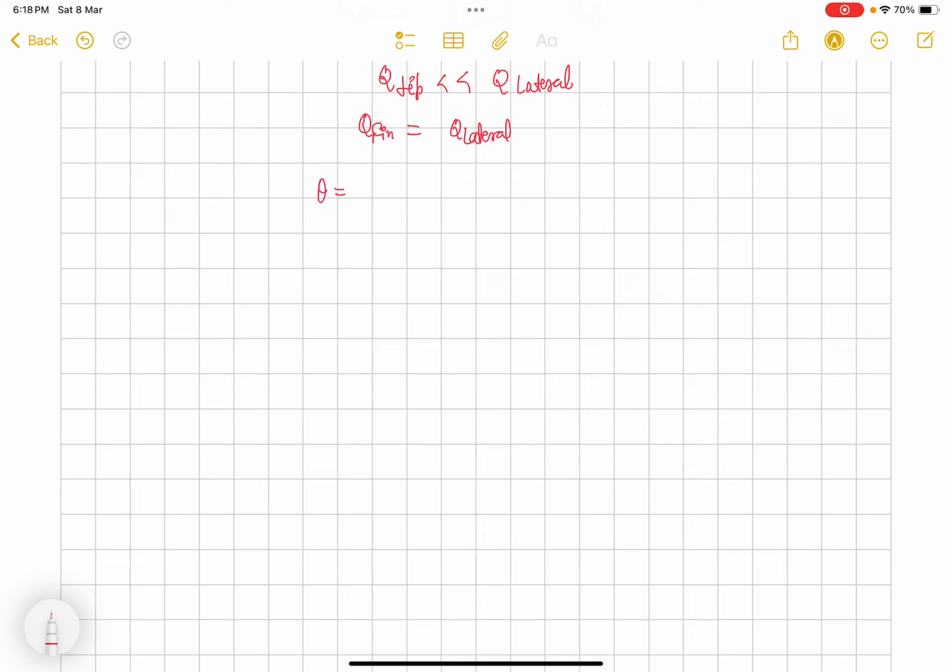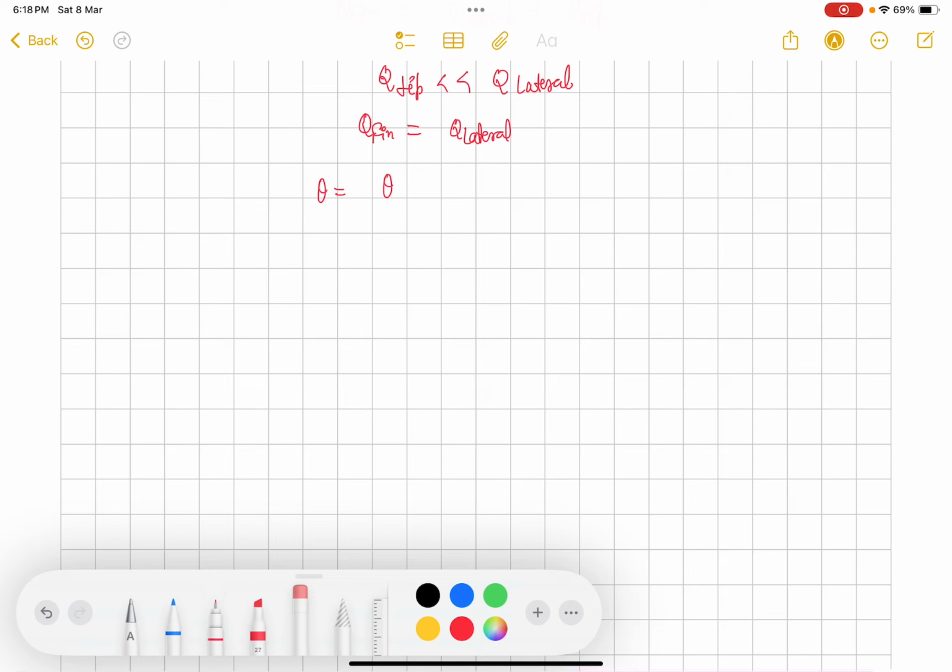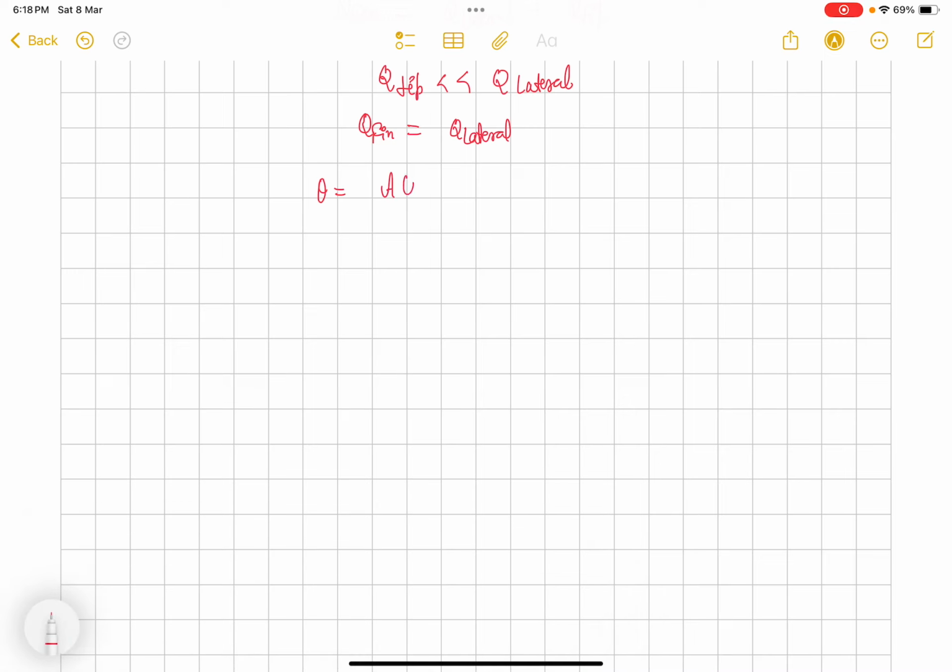Okay, so again we should start with that solution. I am following from the Cengel heat transfer book, and in that it is convenient to use this form of the solution, this form of the fin heat conduction analysis that we did at the start, as A cosh(mx) plus B sinh(mx).